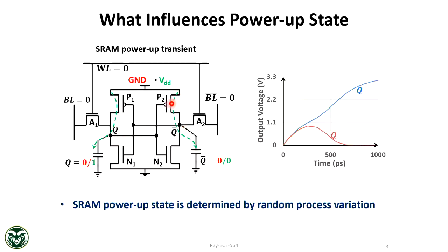So you can change the threshold voltage of the transistor by preferentially aging, or put your data on, so one will be on and another is off, and then apply radiation and other things to cause a preferential difference between these two transistors to imprint the content.